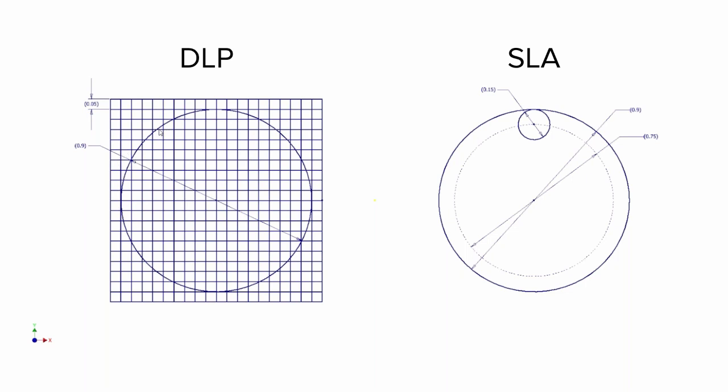So it all lines up okay on the DLP printer when you're at somewhat of an even slice. You can see, over here in the sides and tops of the circle, we line up with a pixel pretty well. And then you can see the software of the DLP printer is going to decide if it's going to turn a pixel on or off. So this one's going to be on.